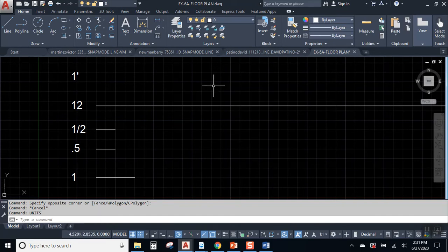AutoCAD right now, by default, is set to work in whole units and round to the nearest 10,000th. As I move my cursor around, those first 2 numbers on the XY axis are changing, and that's the level of accuracy we're talking about.